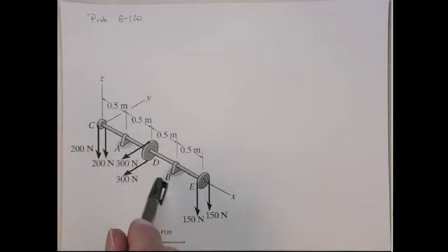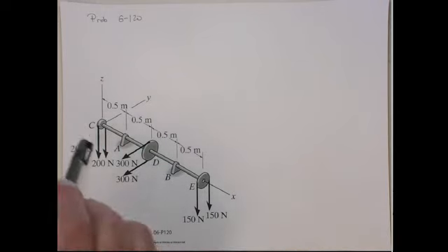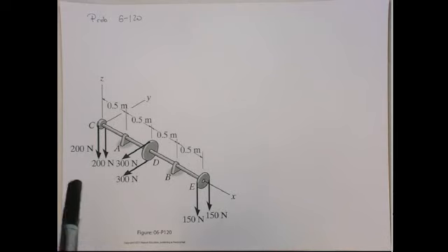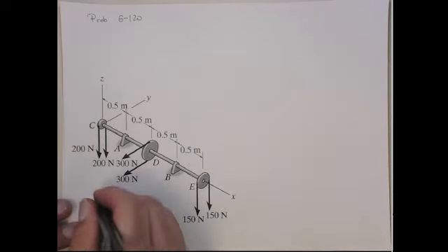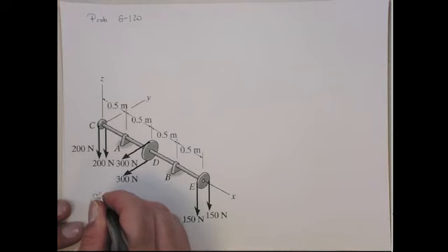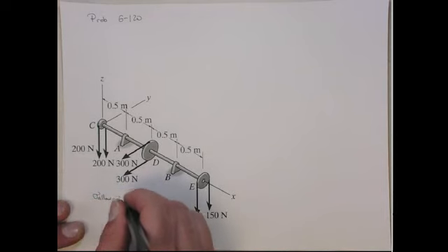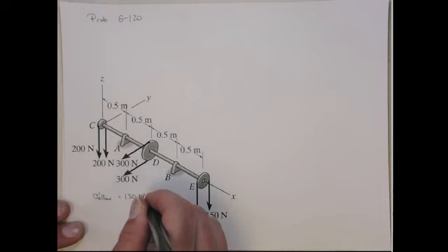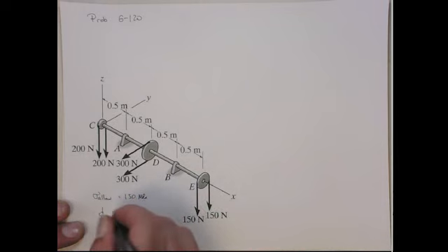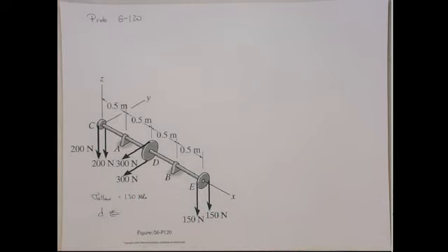The reaction forces at A and B hold it in equilibrium, at least in every degree of freedom except for the rotation about the x-axis, obviously. And you want to find, well, the allowable stress in the shaft is 150 megapascals, and then your job is to design D, the diameter of the shaft. Since it's a circular shaft, the bending planes are going to be coincident with principal axes, obviously. Okay?